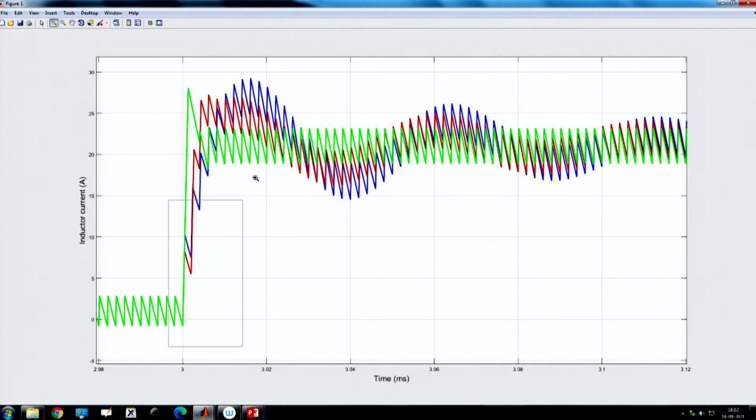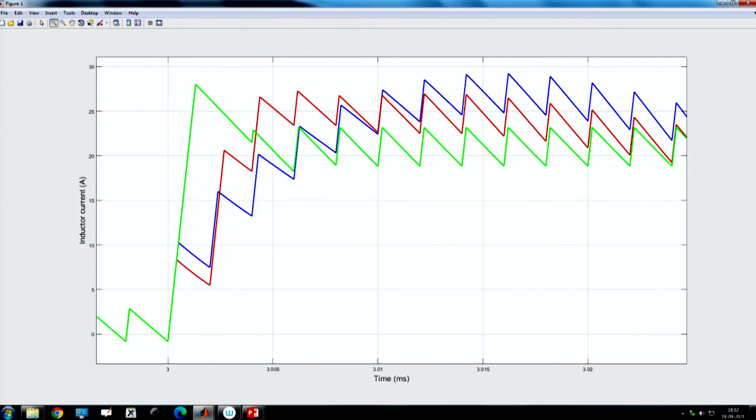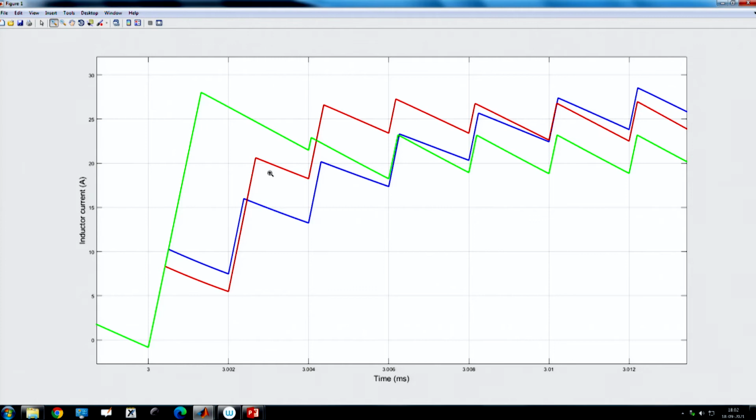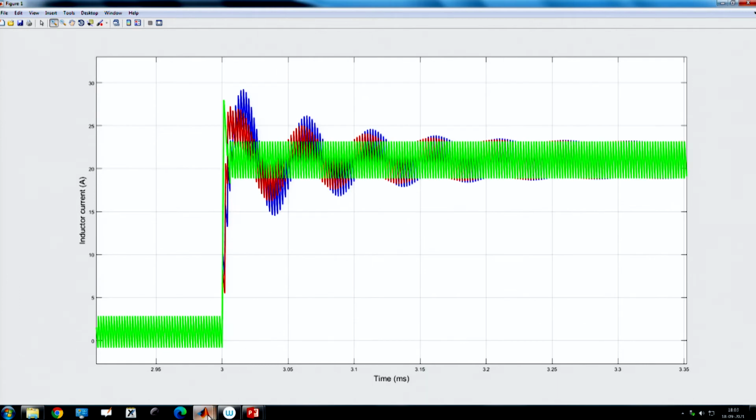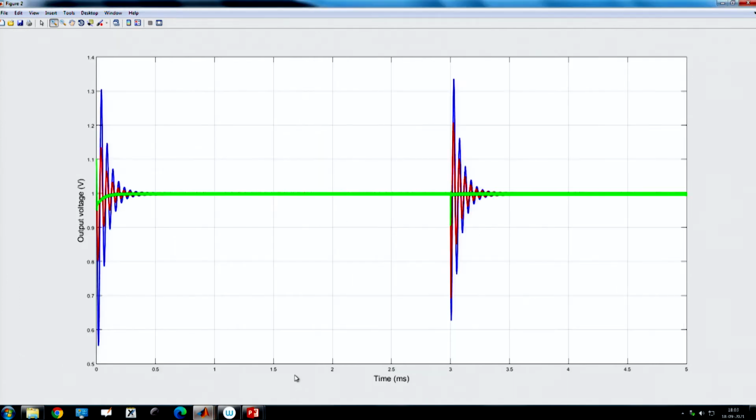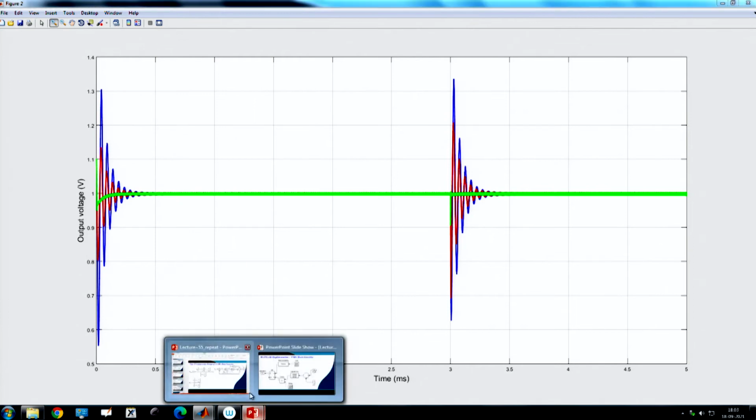So, you will see the difference comes in the fast recovery time, since the small signal model requires low duty ratio perturbation. During the slew up process, there is turn on and off happening, and because of that it slows down the transient response, whereas the large signal tuning allows duty ratio saturation. You see it is turning on for quite some time and then turning off, and it is coming to the next operating point in almost one switching cycle. So, it achieved almost time optimal recovery. Now, this large signal tuning can drastically improve the transient performance compared to the small signal tuning.